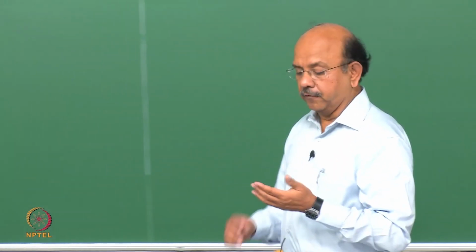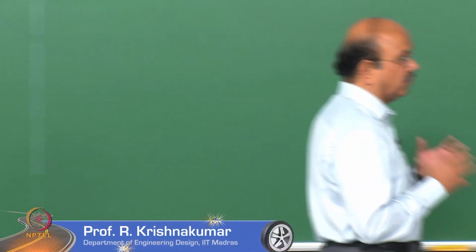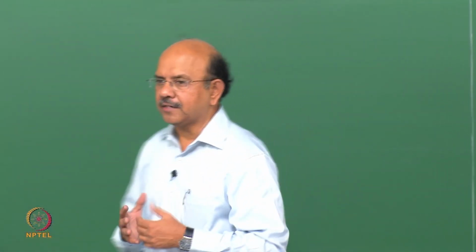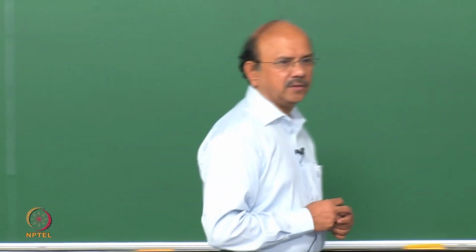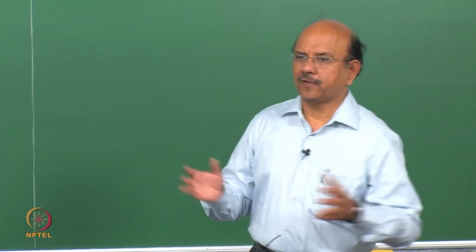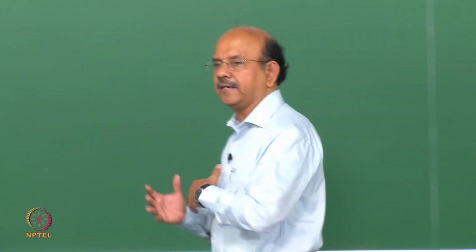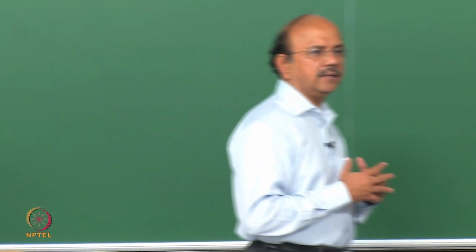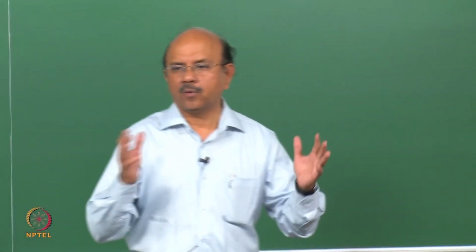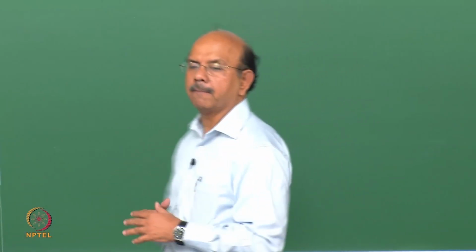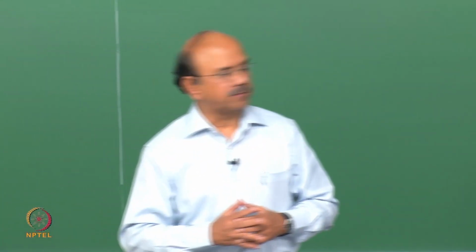Okay, in the last class, we were looking at subjective and objective evaluation. We'll continue this topic. This is probably one of the most important topics, especially for people who design vehicles. They want to understand how to satisfy the driver. In other words, that is what we call subjective evaluation. Usually there is a jury of drivers, 6-7 people, who conduct a number of maneuvers and then answer questions in terms of ratings. For example, there can be a 1 to 7 rating for a question, 1 being bad and 7 being the best, and so on.